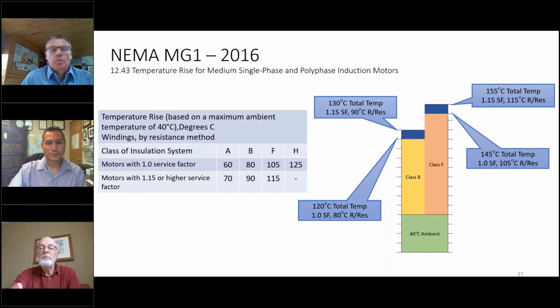If you just sit there all day long, keep hitting that start button, you're going to burn out the motor. If something is causing it to trip, every time you start a motor, it absorbs heat. That graph I showed about the 600% inrush current, that's a lot of heat going into that motor. Unless that motor starts to turn, it has no way to dissipate that heat. So it could kill the motor eventually.